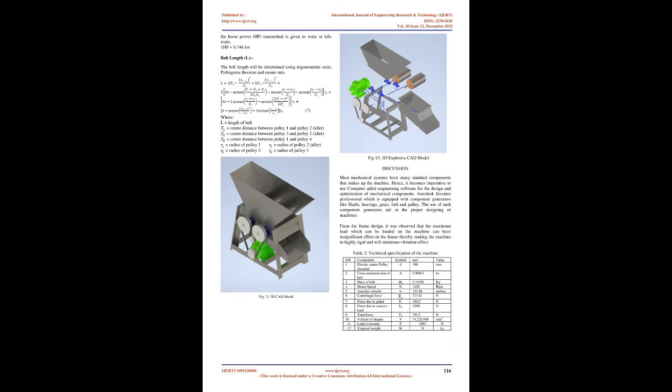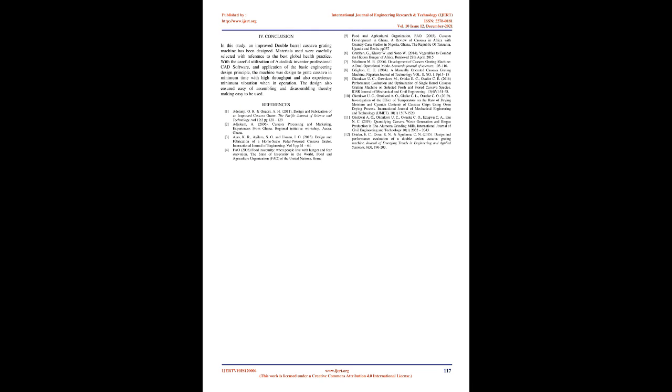Design considerations. The consideration for the design is to attain lightweight with high rigidity, easy installation such as assembly, disassembly and operation, and cost reduction, and also to achieve reduced grating time with high throughput. Design approach. From the evaluation of the forces, determination of the bearing reactions, maximum bending moments, and other stress analysis of the shaft were performed using Inventor Professional software, educational license, and are shown in the figures below.